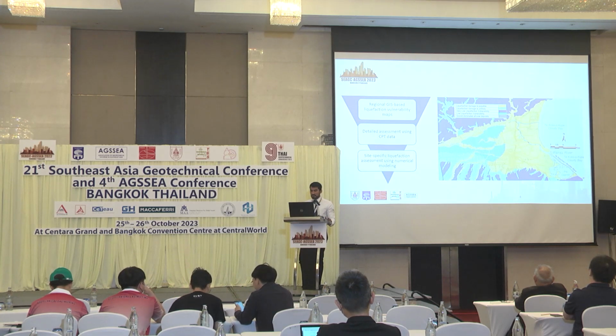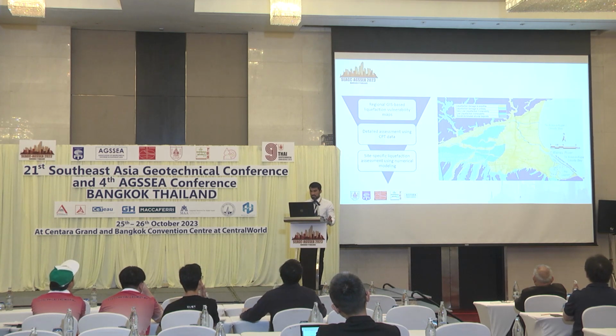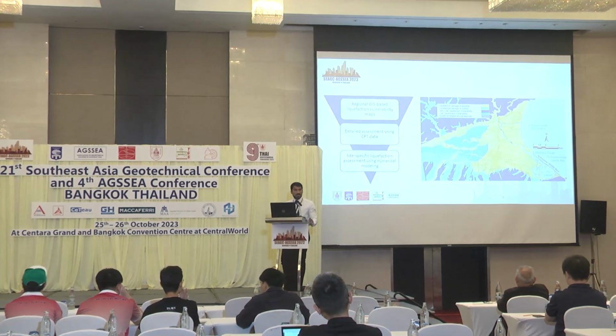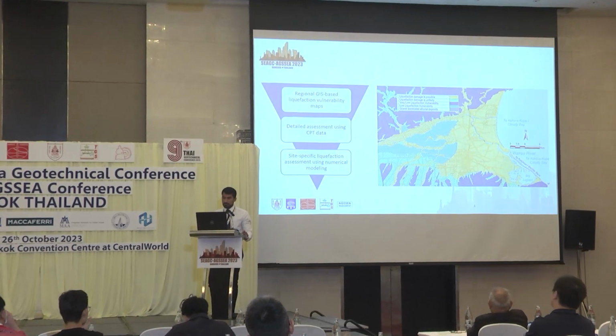As you can see in this figure, in the yellowish part, liquefaction damage is possible, while some of the other parts, which are dark blue, are rocks, where liquefaction damage is not possible. There are also some areas where we can say with certainty that low liquefaction vulnerability will be there. And the hatched cross-section in this one shows that gravel-dominated soils are present, but there is still a possibility liquefaction will happen, and it has also happened in the previous earthquake in 2016.